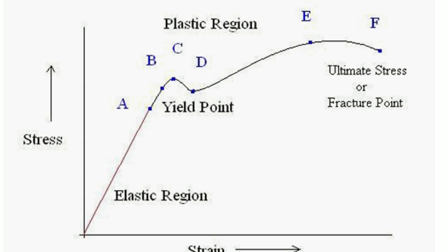Now what is happening? From O, it goes in a straight line up to point A. So what is the portion O to A? This portion is absolutely straight, where the stress is proportional to strain and the material obeys Hooke's law. The value of stress at point A is called the proportional limit.